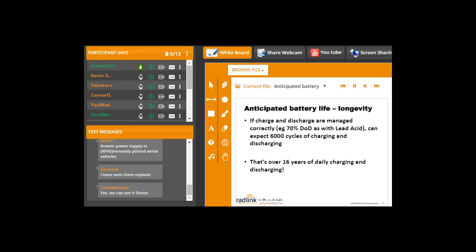What happens is very many people don't even flatten the batteries before they chuck them in the bin. So the batteries, if they were crushed, they would short circuit, and there's a risk that if the cables are too thin to which the thing is connected, there's a risk of overheating and then a fire. And of course, we're talking about LFPs here, but other lithium chemistries that we mentioned earlier, like the cobalt or the manganese and so on, they're even worse. They do leave behind some residual toxic chemicals.